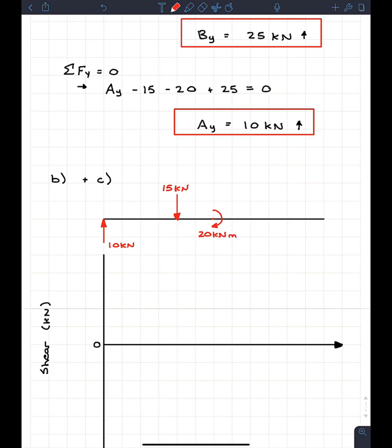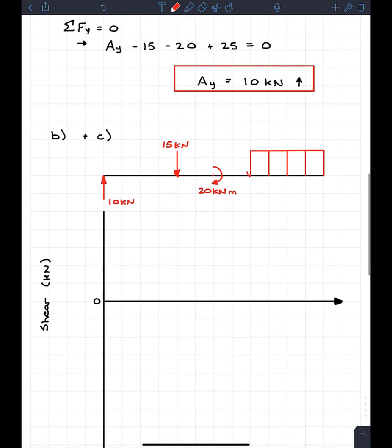And then finally, near the end of the beam, we have a distributed load that comes across nicely across the beam like this. And I don't care about where F1 is or what F1 is, because when I'm creating these diagrams, the only thing I'm going to be interested in is the slope. And the slope here is going to be 10 kilonewtons per meter, or you could say the slope or the magnitude, so I'm going to put 10 kilonewtons per meter. So that's what I'm interested in.